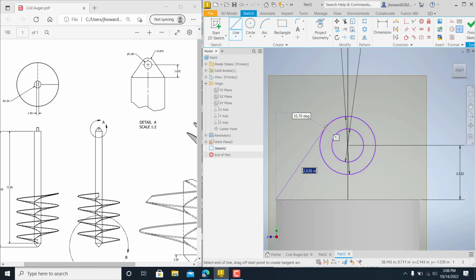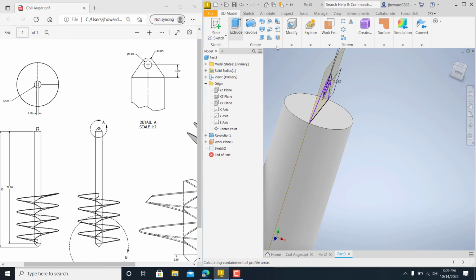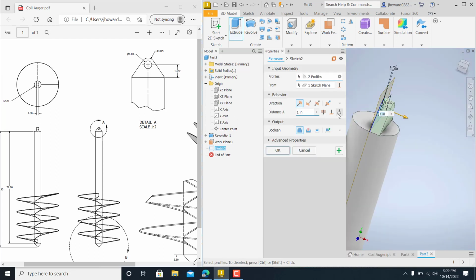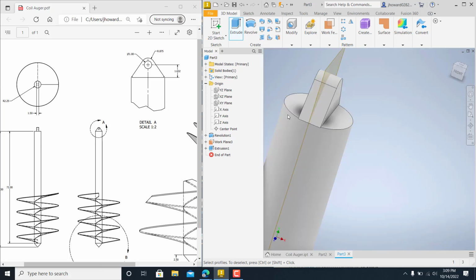Make sure it's tangent. See that little tangent constraint that popped up there, the little symbol? It's very important. And right there on that point, come up here, and again right there it pops up. If it doesn't, make sure you use these constraint tools, and then line, I just close it in just to make sure. Okay. Trim this out, finish your sketch up, and then we're going to extrude it. And you want to do the mid plane, goes on each side equally. It's 1.5.